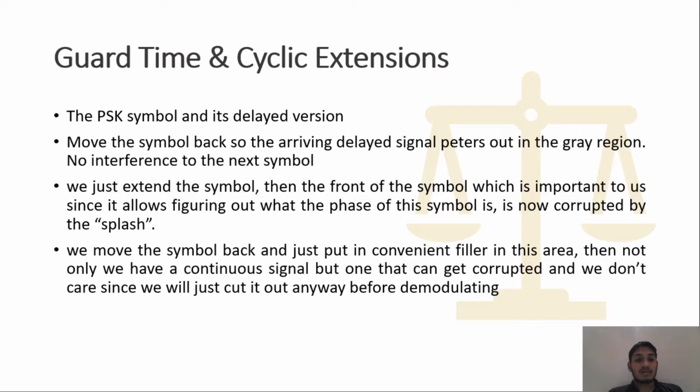Move the symbol back to the arriving delay signal, pushed out in the gray region. No interference to the next symbol. We just extend the symbol at the front, which is important to us since it allows us to figure out what the phase of the symbol is.